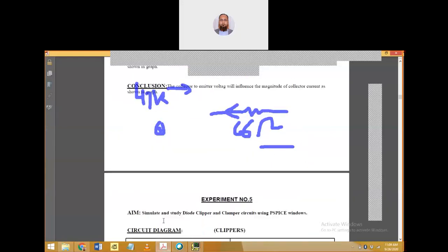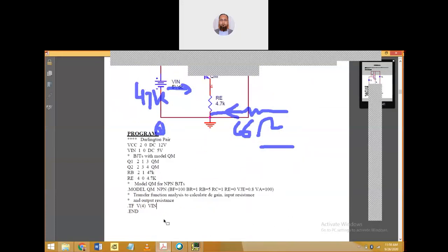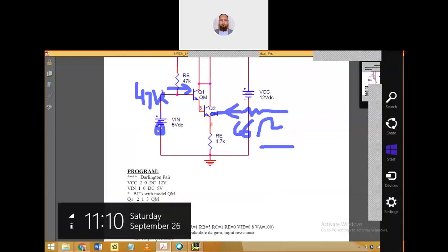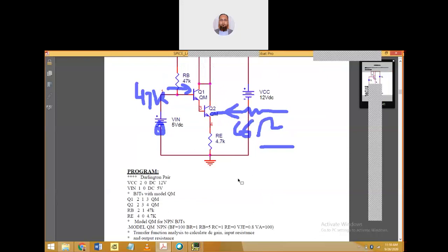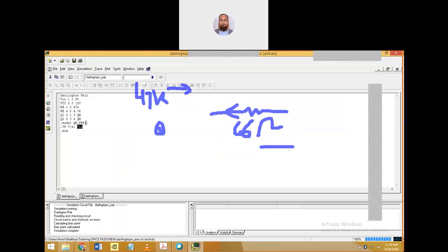So let's see applying an AC signal. Yes, but before that, what is left is that I did not give any values for the NPN transistor. When I write NPN and leave the brackets like this, it means that the software will automatically take the default parameters and simulate it.